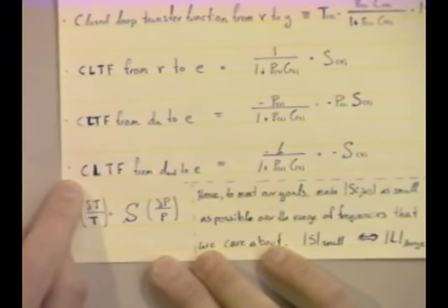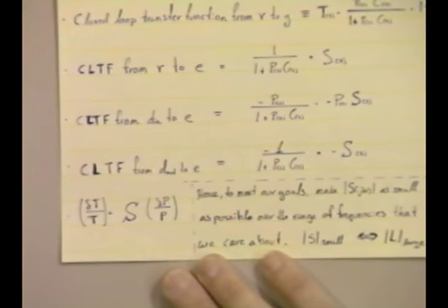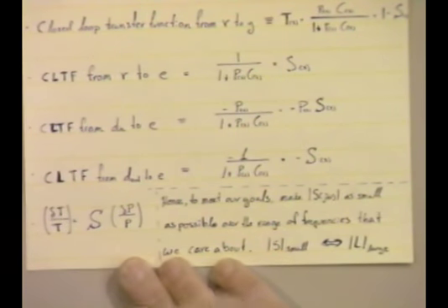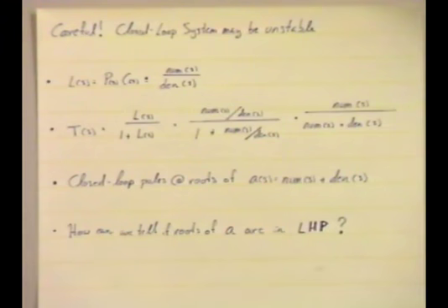From this, and together with these results, we realized that the obvious thing to do to get the benefits of feedback is to make the sensitivity as small as we can. That's equivalent to making the loop transfer function as big as we can. Okay? So, oh, sorry. Okay. So I hope that's clear to everybody at this point. The only problem that we have to deal with, okay, is actually a very serious one, which is the following. When we add the controller and we make the gain of the controller large enough to meet our purposes, okay, we have the risk of making the system go unstable.